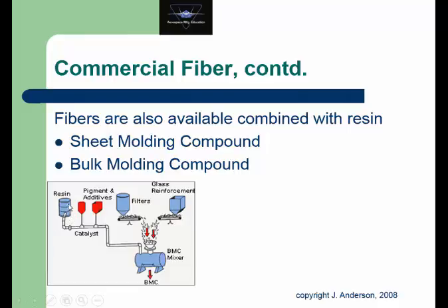have a resin reservoir, so we're feeding in resin, and we're adding to it catalyst and then pigmentation if we need it for color, or any additives in there for things like oxidation resistance. So then we take that resin and we feed it down to a high viscosity mixer, or high shear mixer it's called.